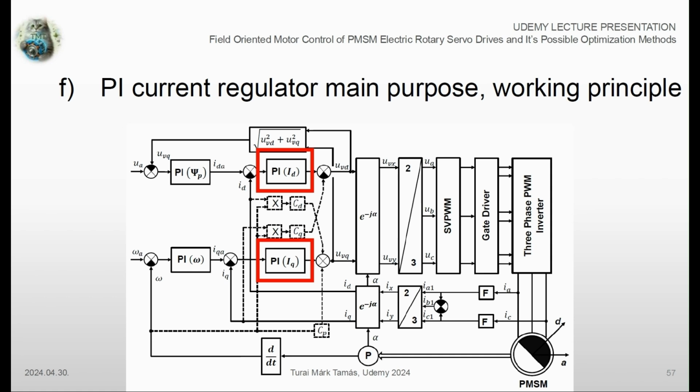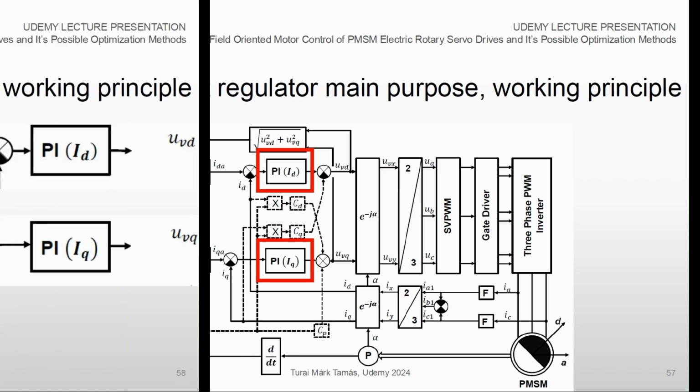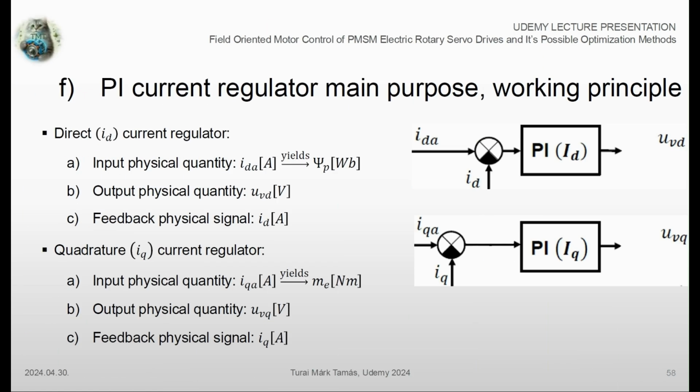However, it is responsible for constantly adjusting the direct current component value to achieve the desired resulting flux in the electric motor. If you feel a quick refreshment would provide a better understanding of this topic, check out slide 24, where you can see how the flux in the D direction can be altered, alongside the pole flux of the permanent magnets. During this video series, we would like to control a surface-mounted PMSM motor variant without a field weakening control algorithm. We are going to shortly align on the relevant input-output current regulator interface physical dimensions, as we did in case of the speed controller.